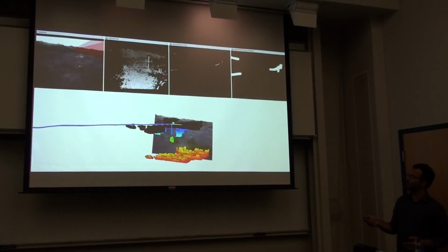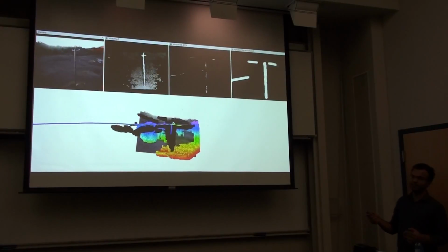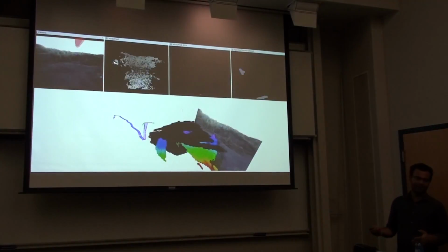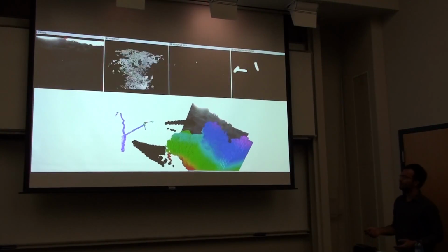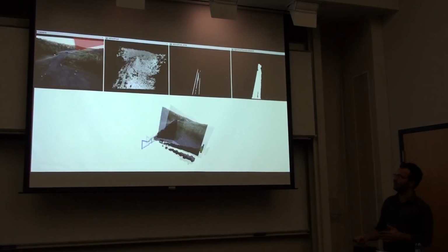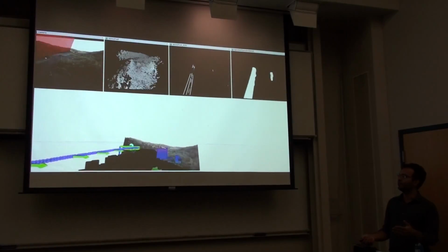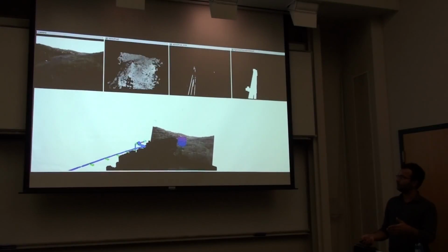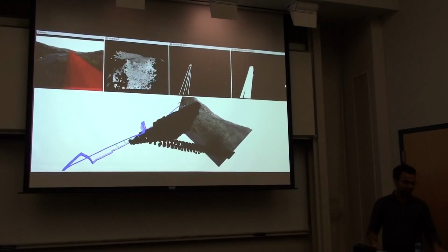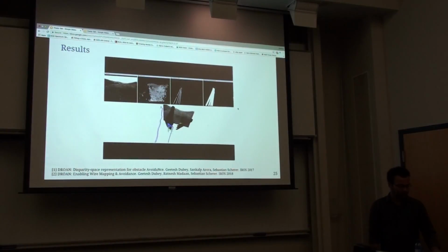So what this video is actually demonstrating is that you can map the things seen in the disparity image along with the things seen in this monocular image using voxel grid mapping, but done in an efficient manner, just using images. So now when this thing turns out, we start following the wire, and then the idea becomes very clear that we can't really reconstruct the depth, but we can be conservative about the depth if we don't have enough viewpoints to reconstruct it. And then we eventually close the loop with this method in the third part of the talk.